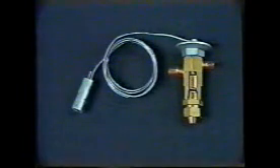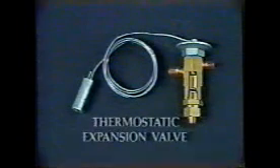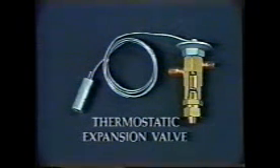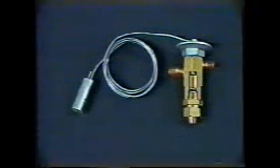Let's look at one kind of metering device that responds to temperature. It's a very common type used in refrigeration systems. This is a typical thermostatic expansion valve. It has been cut away so you can see inside. The thermostatic expansion valve maintains a constant degree of superheat by regulating the flow of refrigerant to the evaporator.